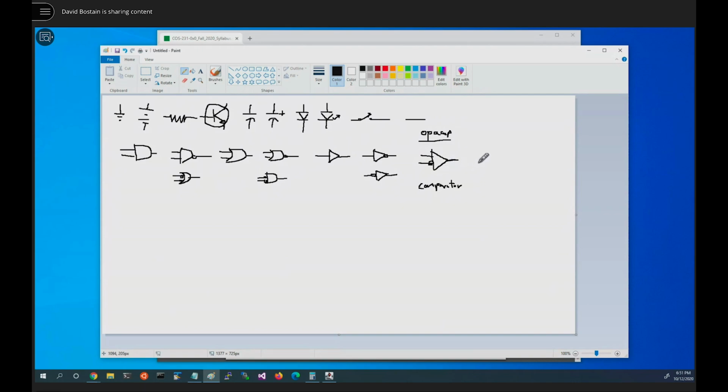Internally inside the 555, we saw a transistor. We saw a different picture of a resistor, which looked like this, just a little square box. We saw an RS flip-flop. We're going to talk about how they might be designed. And most of the rest of it was simple wiring that goes on inside there because a lot of that chip is external. So these are the things that we have looked at and have some understanding of. But now we need a set of schematics for the flip-flops and latches we've been talking about.